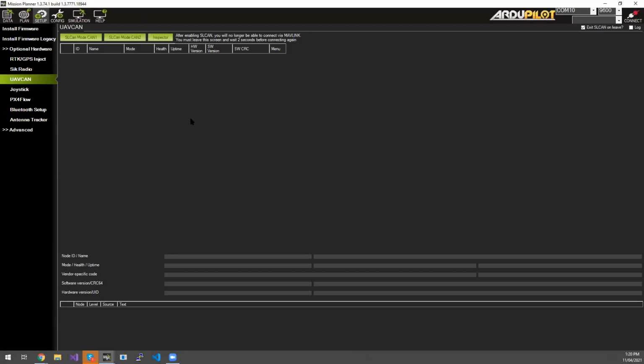Although Mission Planner doesn't directly support processing those logs, I do have apps in the background that support processing those SLCAN logs into, say, JSON files or Excel files, depending on the data format, and actually analyzing the data afterwards. Mission Planner doesn't support that out of the box, as it's probably a more advanced topic, but if you needed a SLCAN log off the bus while viewing the data, you could possibly review what you saw during the logging using Inspector as an example, later on.